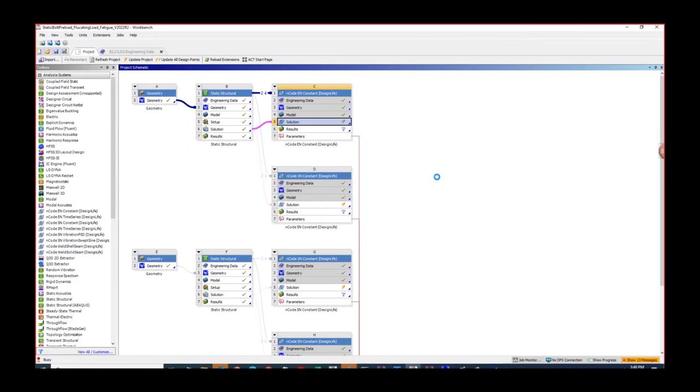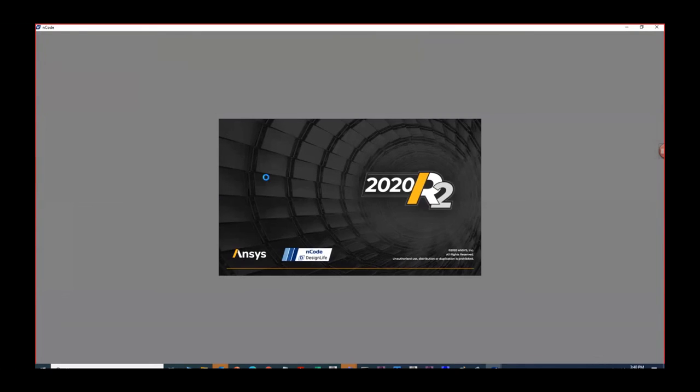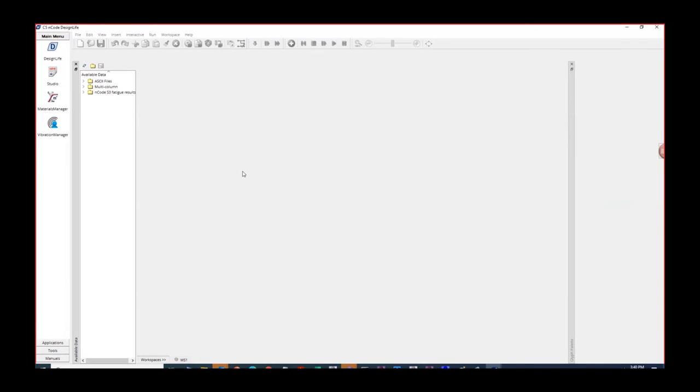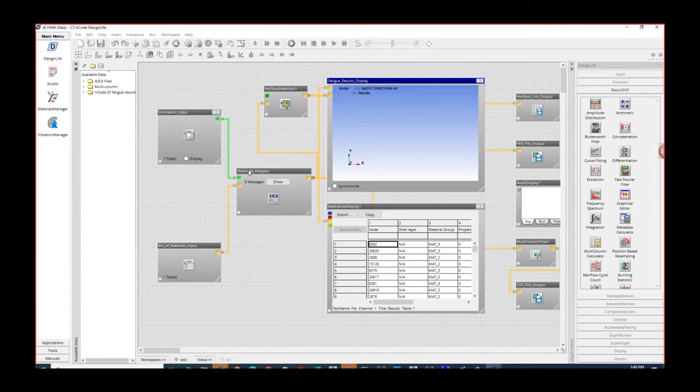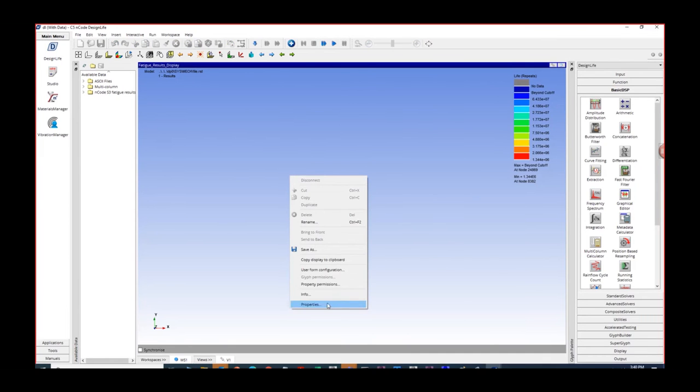Next, I'm going to demonstrate the results for the same stress state from the EN analysis, using the plasticity correction method, rather than using the plastic strain computed from the Ansys FEA solver. The problem setup is exactly the same as I explained in the previous problem.